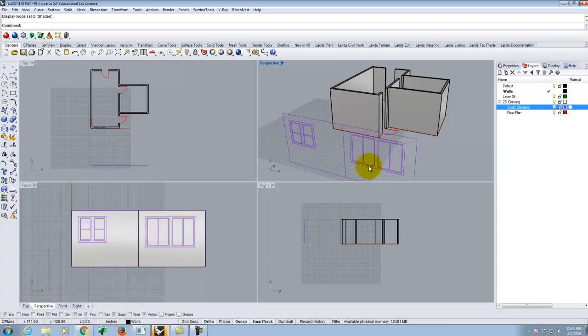And then as you go along in the semesters, it starts to make a little bit more intuitive sense. And so what project does is it's essentially like a projector where you start at a place and you take some lines, and if those lines were to exist, it would cast those lines onto a surface that's behind. Okay? And so what we have to be careful of is the line through which it's going to project is always the view that you initiate the command in. Okay? And so this is the tricky part.